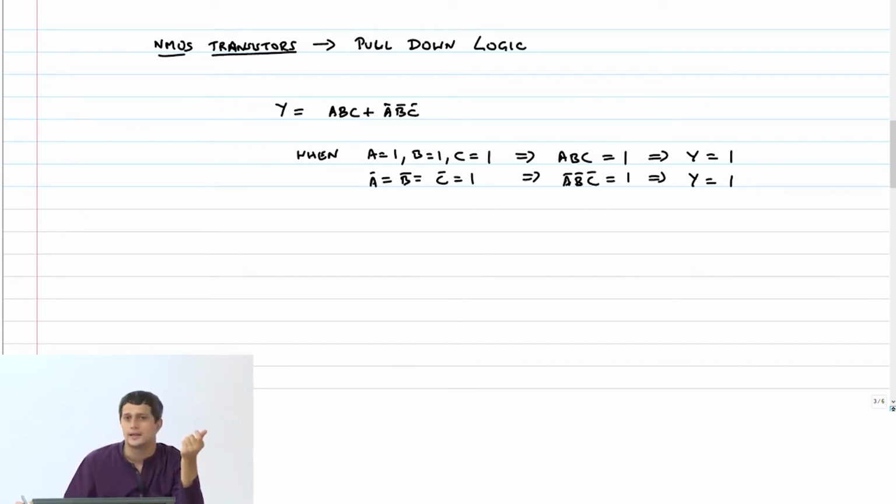Unfortunately, the NMOS transistor cannot pass a logic high, right? Why are we using the NMOS transistor? Because the switches are active high switches here. In this SOP thing, switches are active high switches and therefore we are going to use NMOS. Unfortunately, you cannot use it to pass a logic high as the SOP normally demands.